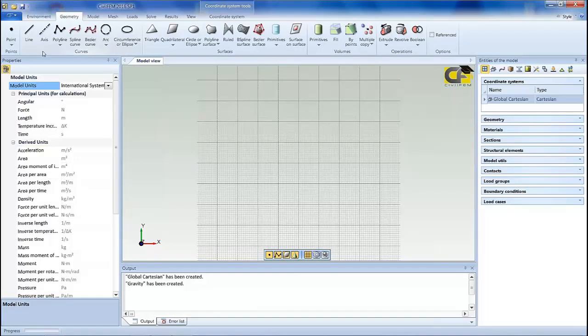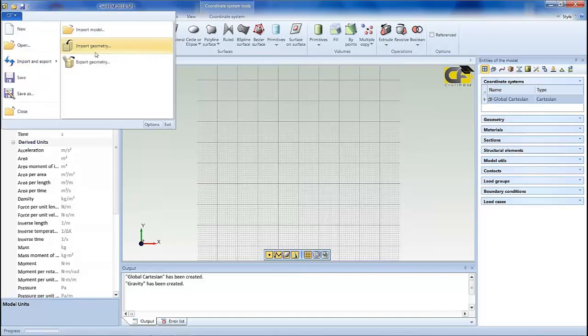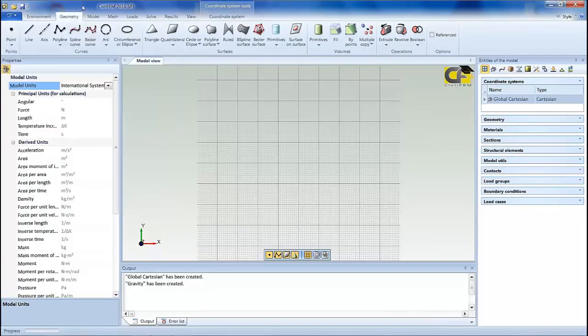And once we have defined our geometric model, we can perform other operations such as extruding, revolving, and Boolean. We'll see with examples how to work with all these utilities. As you can see, you have a complete list of different geometry definitions. If we want to use an external cut, we can also import another model, importing geometry from an IGS file, STEP file, DXF, or Parasolid. So we have other options for the geometry definition.